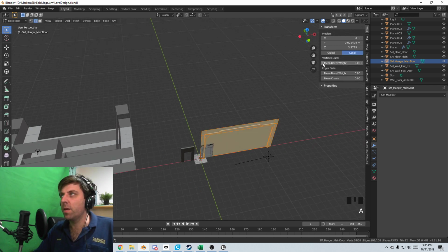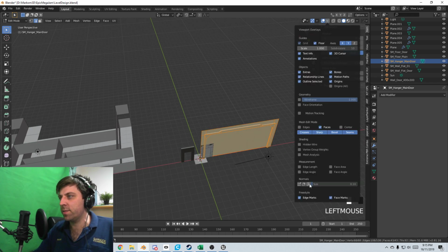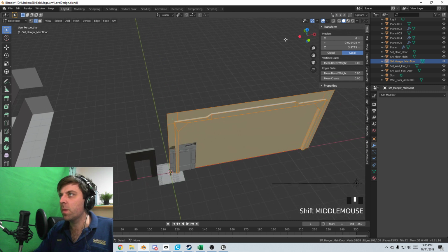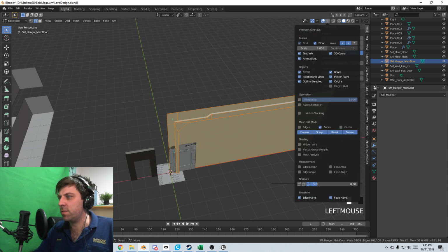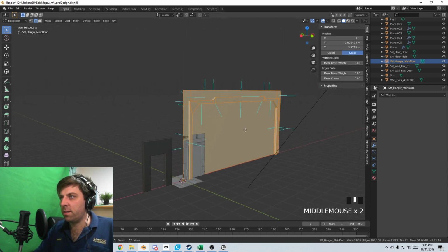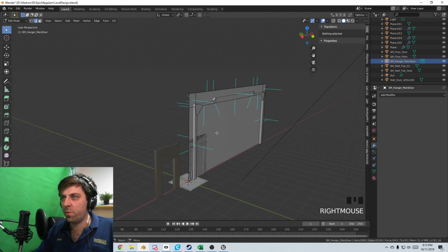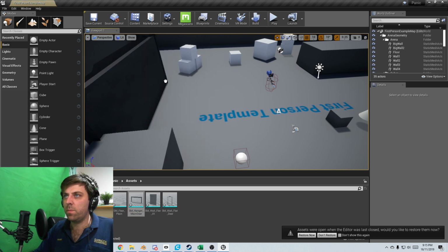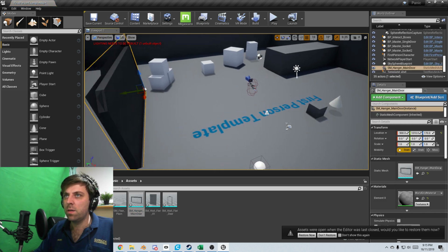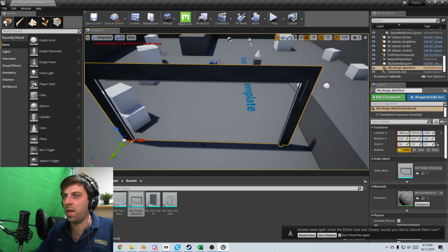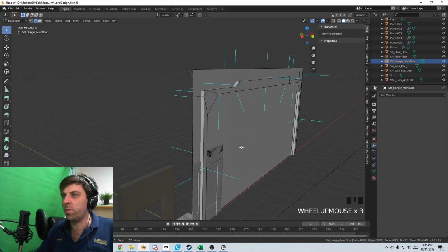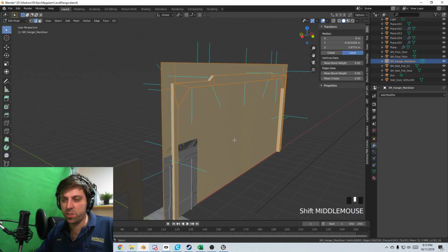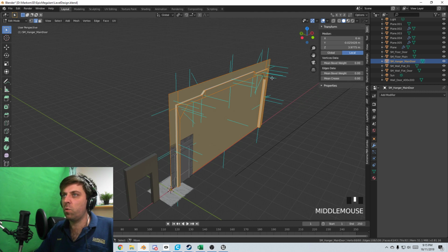Okay. So let's check which way the normals are going, because that's affected me now. Let's just increase the size. So you can see that this here is not present. If I dump this in somewhere, we can see from this side that everything is missing. So I've got to flip the normal. We select everything, Shift N, and there we go. All the normals are now correct.